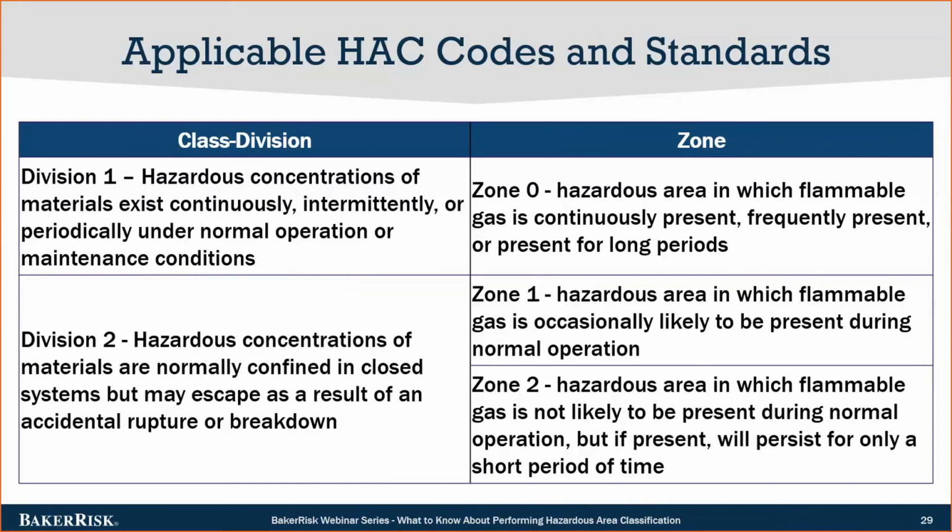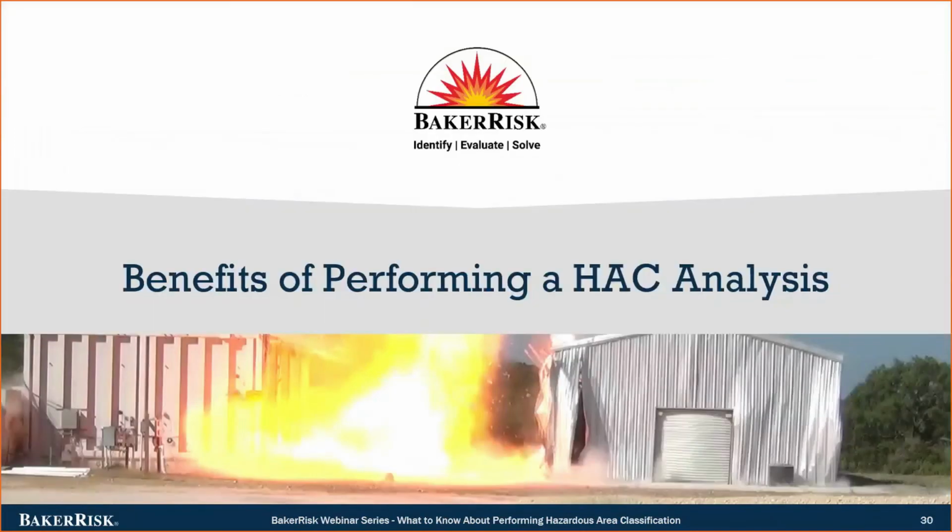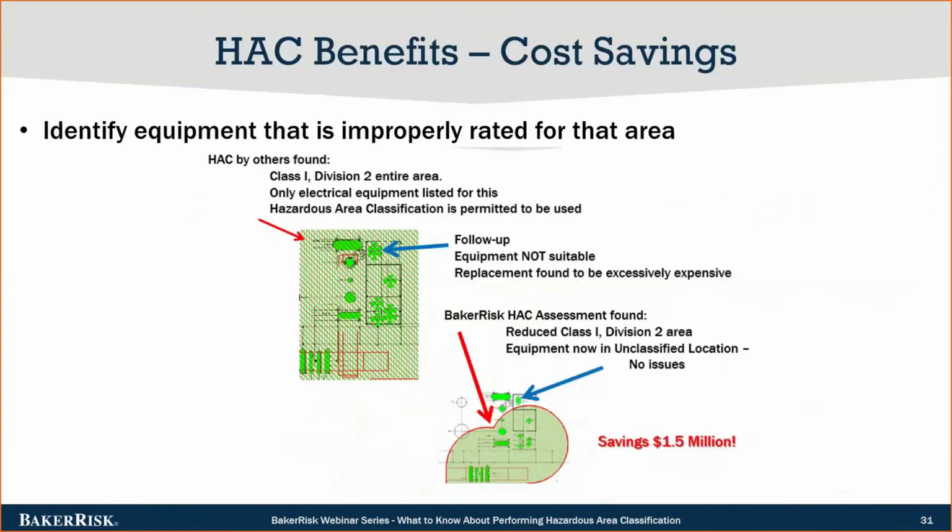So let's look at the benefit of performing a hazardous area classification analysis. Austin? Yes, thanks, Dave. So some of the benefits of doing the HAC using the scenario-based approach. In this example, we had a client where we're working on a project and they had some questions around their existing classification areas. They were using the traditional approach where the entire unit was considered a Class 1 Division 2 area. And in order to expand that unit or to install any new equipment, because it's entirely classified, the equipment has to be rated to meet that area.